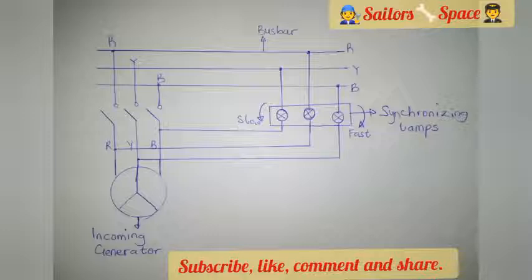This shows that your system is ready to be synchronized. At the same time, the slow and the fast arrow, if it is running slow, that's in the anti-clockwise direction, it shows that your incoming generator is running very slow. That has to do with speed. Now we are checking the frequency.